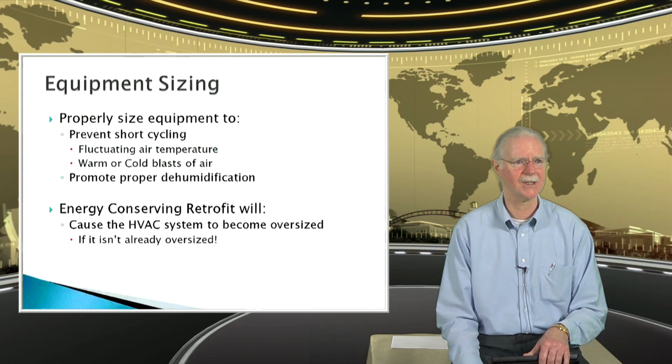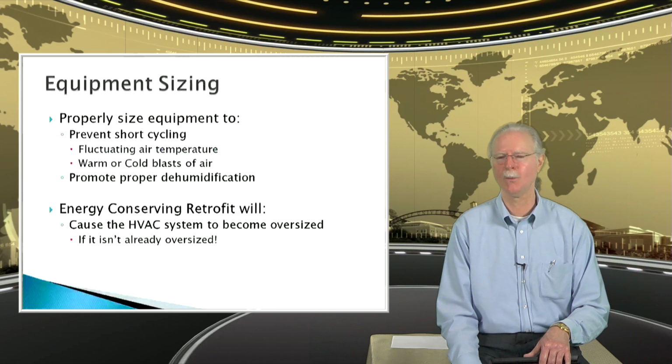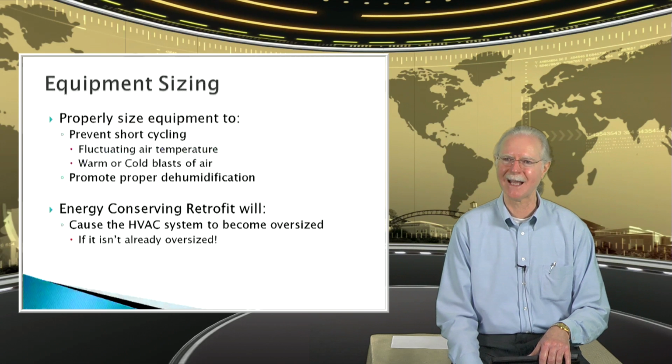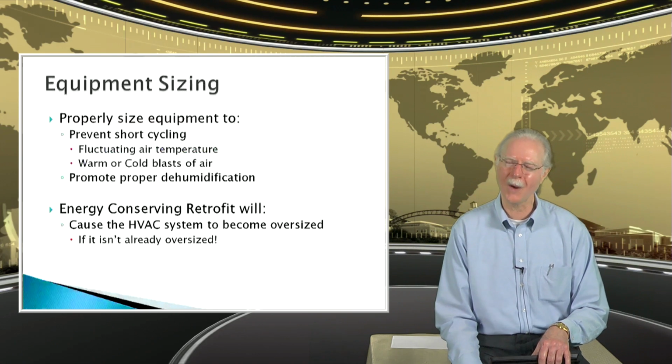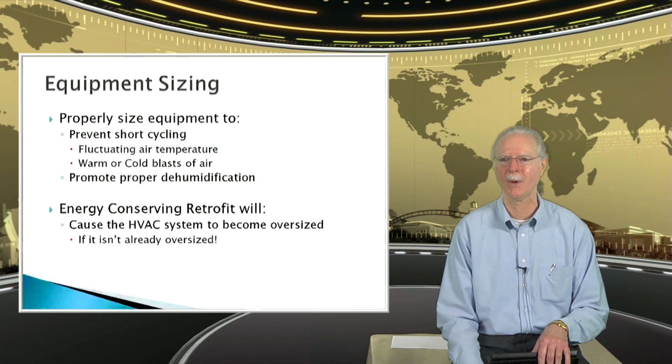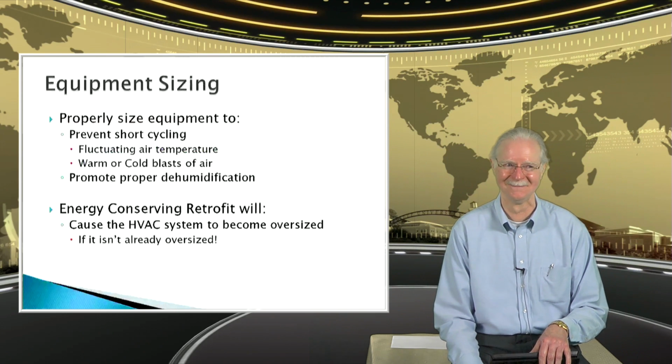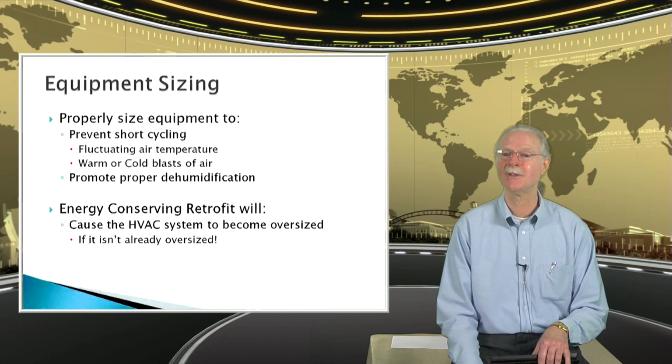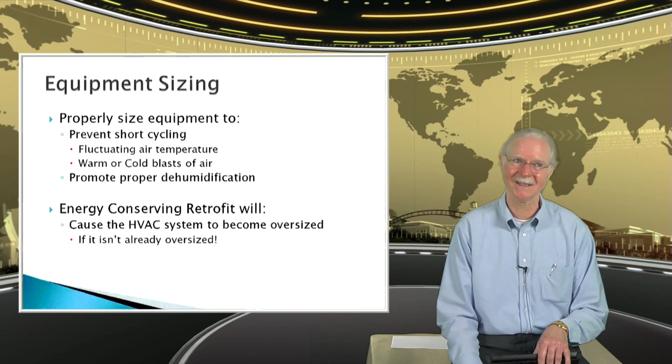Because if you think about it, a furnace is going to be most efficient if it runs 24 hours a day, every day. Heat exchanger is always hot. Now, can we get it to operate that way? Sure, at 0 degrees or -10, that's what you want. But since we are always worried that that won't be enough, we overshoot it, so seldom does it ever get to that point. And if a client calls and says, it's 100 degrees outside, my air conditioner's running 24 hours a day, you should go, great, we did a really good job designing that system. But that's not the way your client often will think. So that's something that gets in the way.